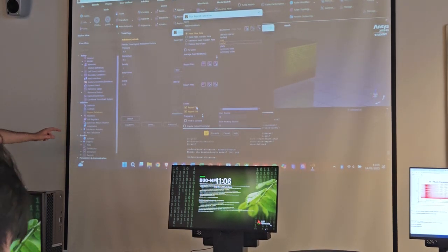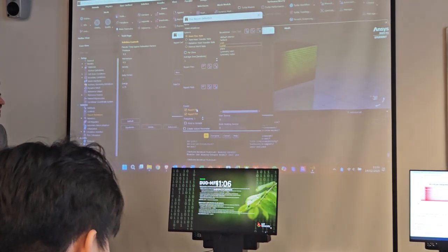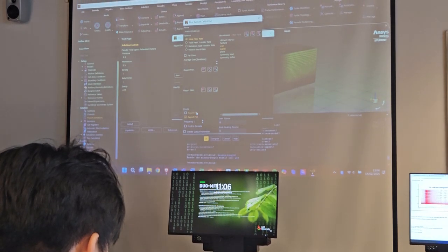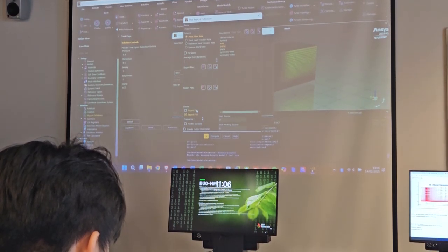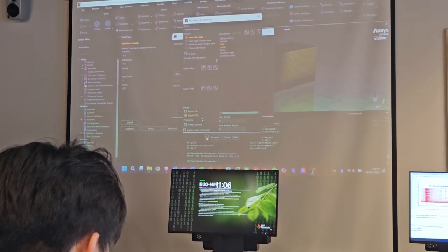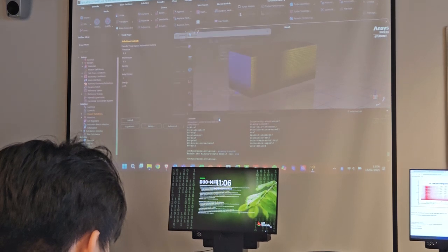Then here you have the options to create a file or a plot. I don't really need a file, so I can just report a plot, so that while it's solving the equations, it's showing the mass imbalance per iteration. And okay. And close.